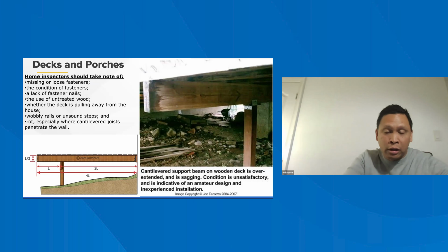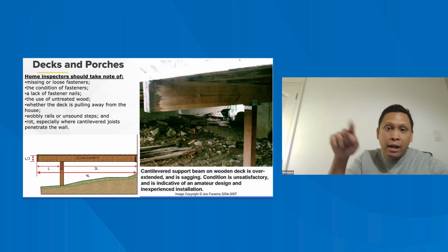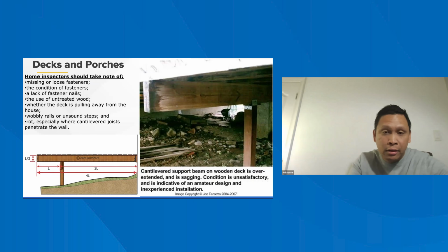We want it attached to a solid surface, but then also note that I said solid. If you see a ledger board there, go inside the house and make sure that the bolts are actually being driven into something solid and not just the OSB band board that wraps around the bottom part of the house, because you will see it happen from time to time. Now just start looking for it, because it's important.